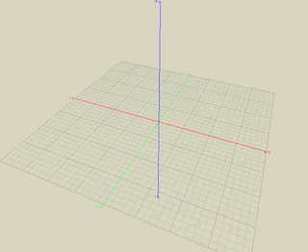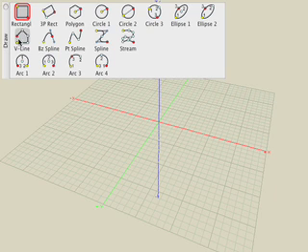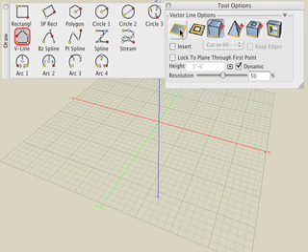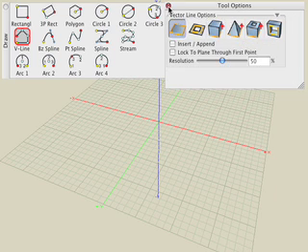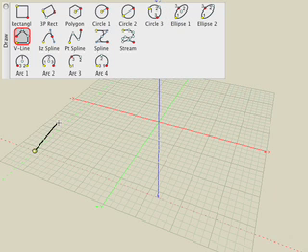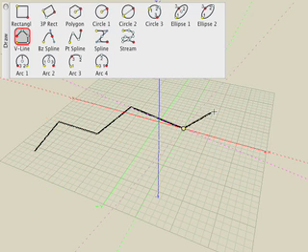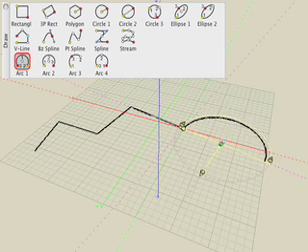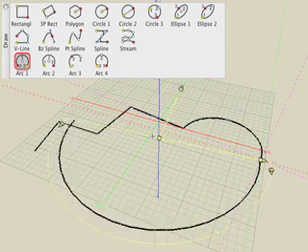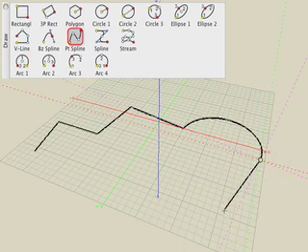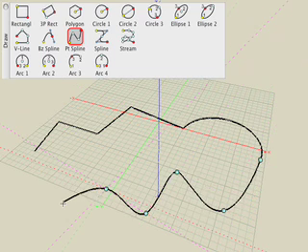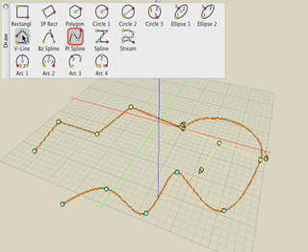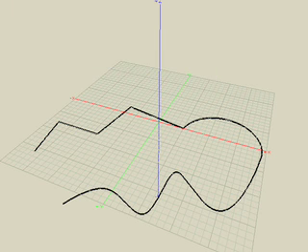Let's begin by drawing a 2D shape. We'll go to the Draw suite of icons, and we'll select the Vector Line Drawing tool. In the Tool Options palette, select the 2D surface icon so we can draw it as a 2D shape. Click a few points for the vector line. Then let's switch to the Arc tool and continue on with an arc. And from there we shall use a spline curve drawing tool and put a nice little curve on there. And then we double click to end. And there's our 2D shape.